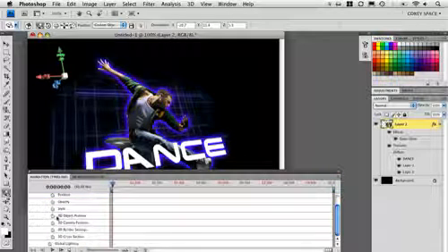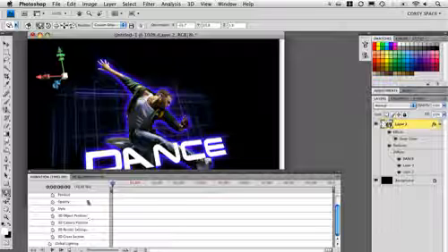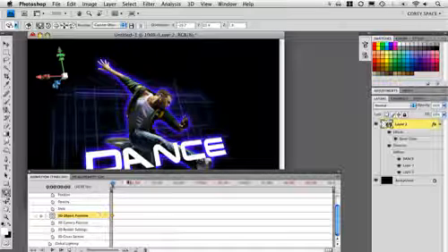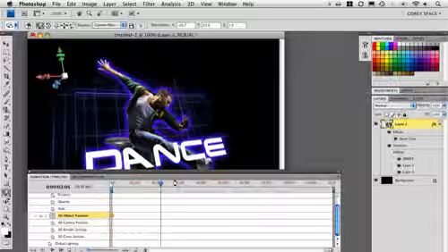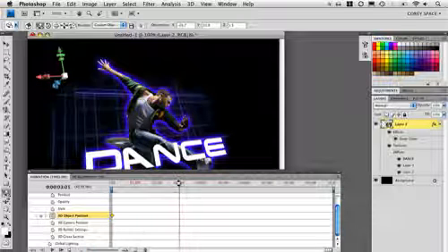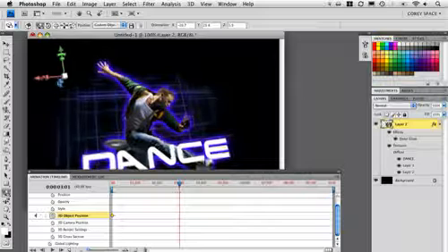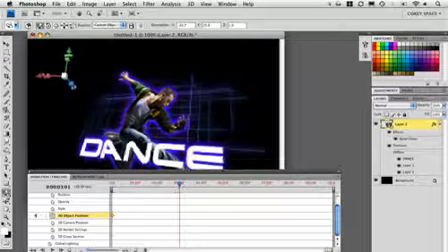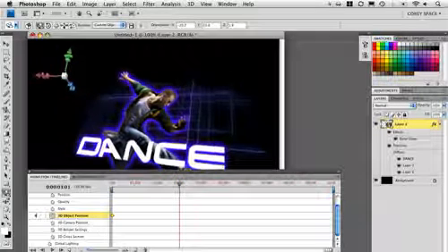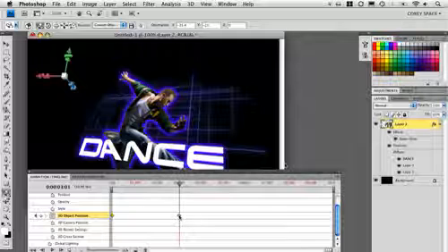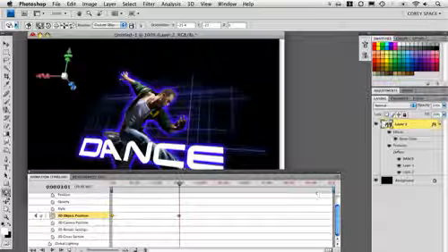So we're going to animate the 3D object position. So in this first position, let's go ahead and lock in a keyframe there for 3D object position, and let's move it down the timeline to about the 3-second mark. I think that looks good. And up inside the file, let's just take our rotate and then rotate that around in 3D. Looks really cool. And notice it automatically pops in a keyframe for that new position.